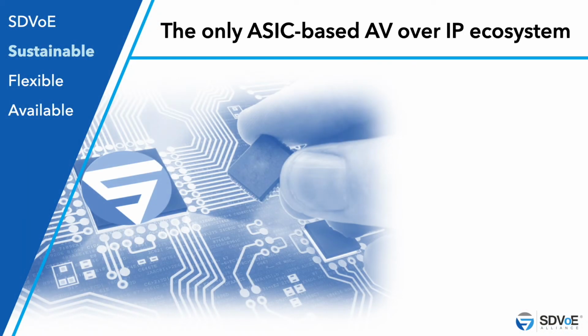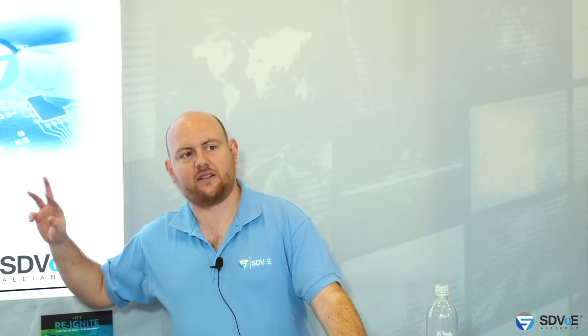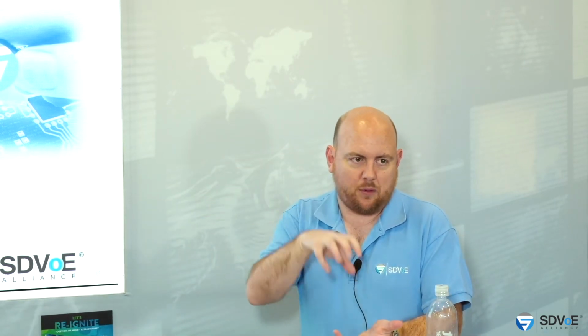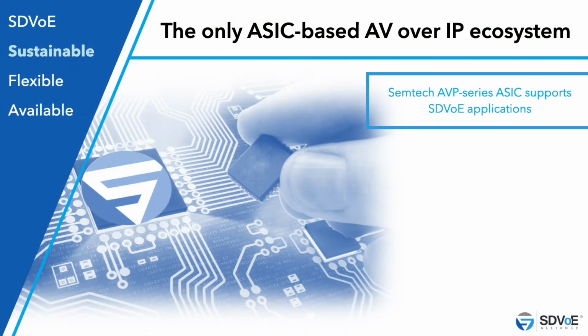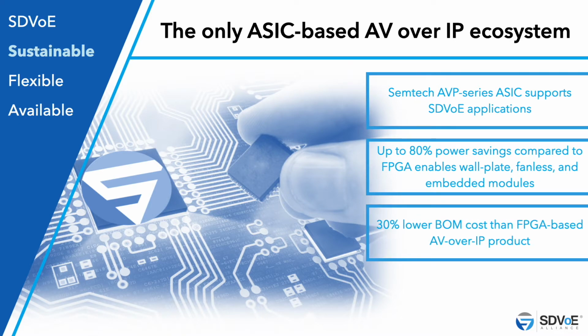So let's get into sustainability. SDVoE is unique in that we're the only AV over IP ecosystem powered by an ASIC at our core. Now an ASIC, that's an application-specific integrated circuit. One of our founding members, Semtech, has built the ASIC that does SDVoE. And that's compared to an FPGA. I'll tell you a little more about those in a few minutes. But an ASIC is a device, it's a chip, that's been carefully designed to perform one and only one function. In our case, it does AV over IP. And compared to the FPGA, which is the kind of chip that every other system out there uses, we're talking about 80% power savings, we're talking about a 30% bill of materials cost reduction.